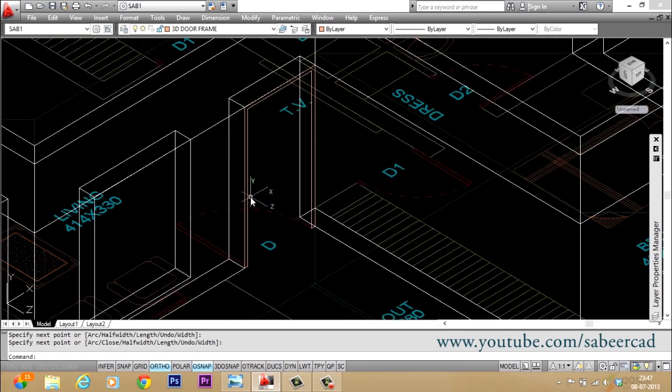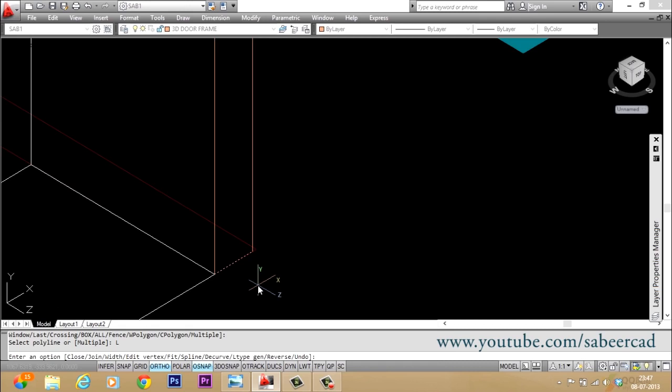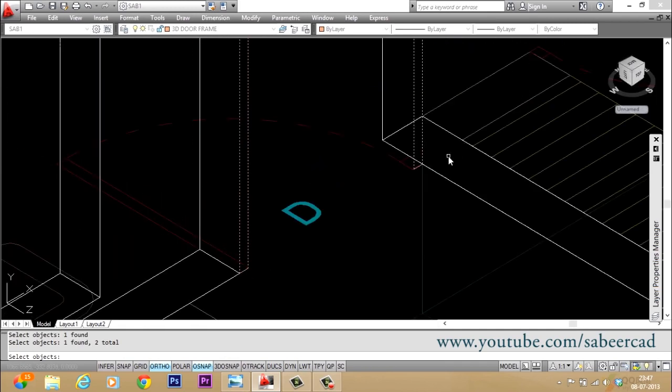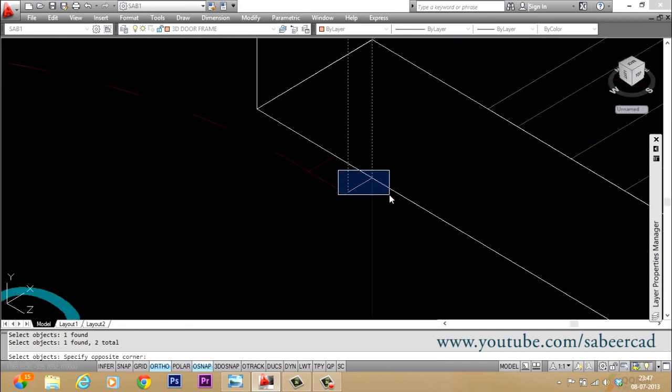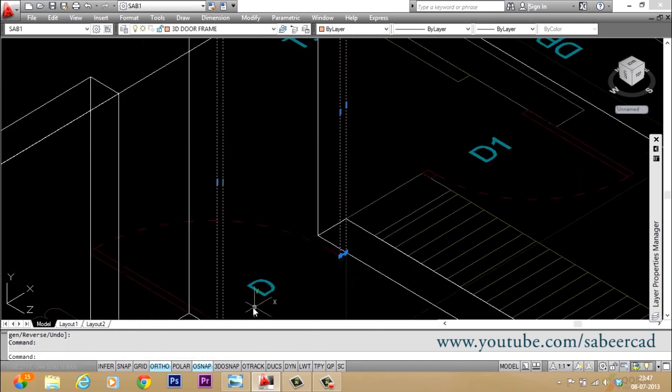Now let's make it a single profile. So I'll go to P-edit, polyline edit, last polyline is selected. So when I type L, the most recently drawn one will get selected. This has got selected. Now you can give join, and I'll select these polylines to be joined along with the existing polyline. So I have selected all these polylines. Now you have got a message that 7 segments were added to polyline. That means you have got a single polyline profile.